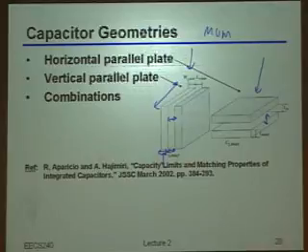What's the number one thing digital guys care about? Well, okay, it is true from a certain standpoint, I agree, it's capacitance, but taking it one level up, what's Moore's Law all about? Okay, yeah, so a bunch of you said a sort of convex combination of what I'm getting at. Remember, it's cost, right? How do you drive down cost? You make the darn chip smaller for the same function. How do you make the chip smaller? You get more transistors per unit area. You get more wires per unit area, right? Well, how do you get more wires per unit area? You make the darn width of the wires smaller, and you make the spacing between the wires also as small as you can possibly make it.